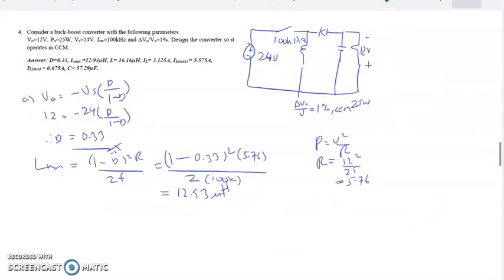If there is no limitation mentioned, in general, when we have calculated the minimum inductor value required for CCM, we should increase it by another 25%. This is a general consideration for practical design, an increment of 25% to make sure that CCM happens at any time in the circuit.